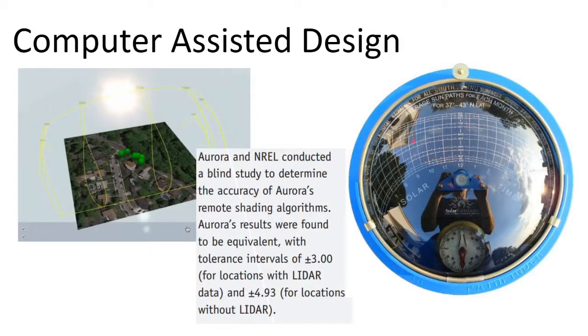You can literally just carve out, based on where these shadows are, a percentage of your solar production for shade analysis. Now, a detailed shade analysis done in a computer environment would actually be calculating the energy on the solar array at every hour of the day and giving it to you in a very detailed, granular report.